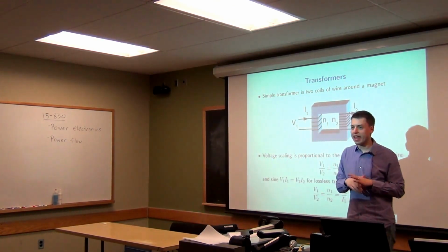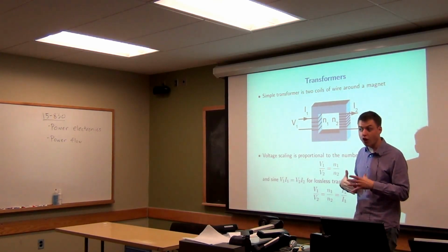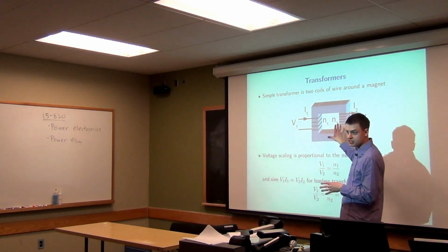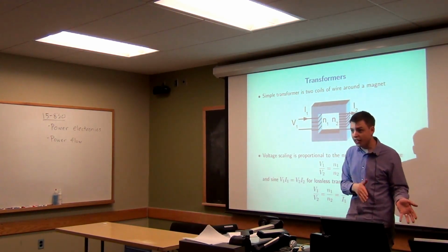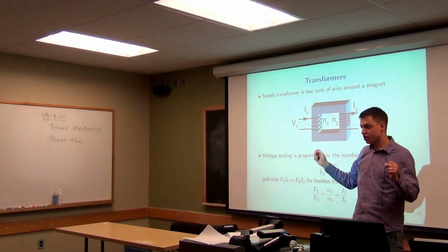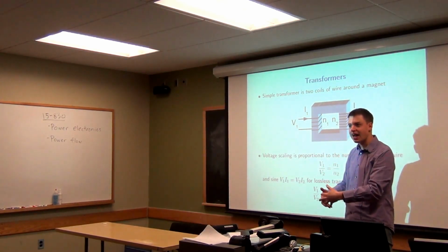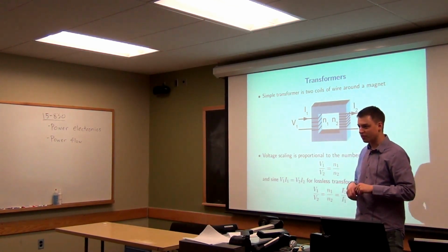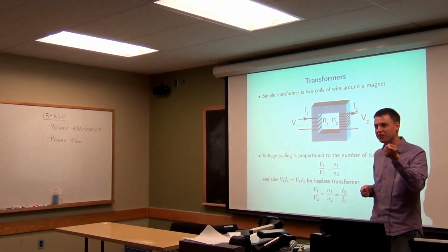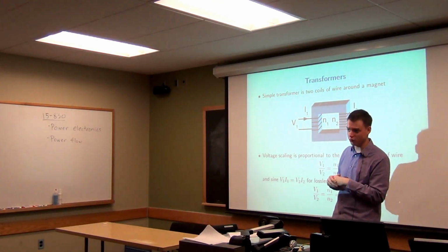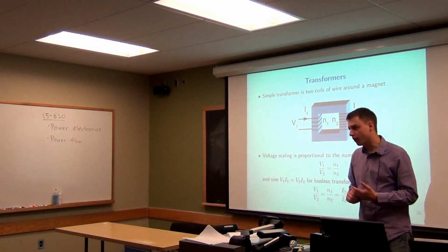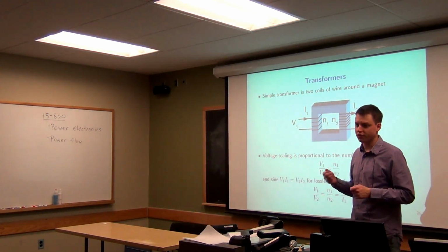And actually, this was a big reason why AC power back in the day really took off. It's because there were these easy mechanisms for converting between voltages in AC power. And one of the big original arguments for using AC power is the fact that we could step up the voltage for transmission, transmit it over very long distances, and then at the end side, step it back down to be at a point where it's safe for people to use. The danger, of course, is when you have high voltage, if you do close a circuit like that, that's a huge difference of potential energy, right? So that's very dangerous. You don't want to go touching high voltage wires. But the advantage is we can transmit AC power long distances without very much loss in the lines.